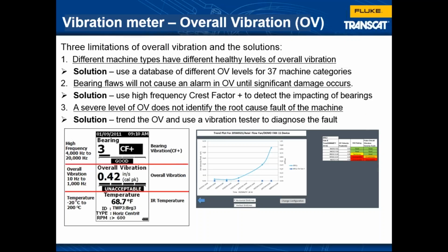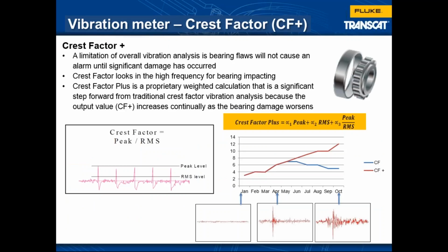Okay, so we talked a little bit about this high frequency measurement. We're using something called Crest Factor Plus. And Crest Factor Plus is a way of looking at that high frequency impacting. Again, I'm not going to get into a lot of detail here, but what Crest Factor Plus looks for is that high frequency impacting of the bearing, and we can trend that over time, and it'll tell us whether the bearings are getting bad.